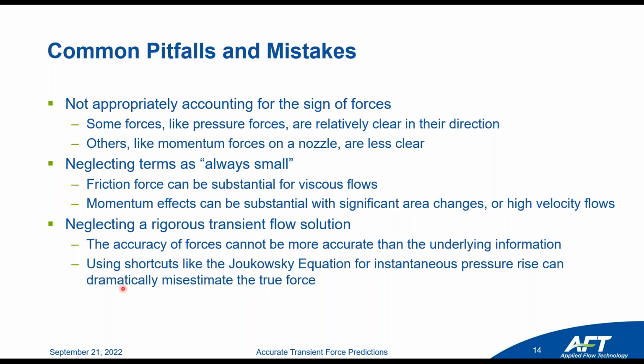That can dramatically misestimate the true force. And I say misestimate here on purpose because you could get a force that is lower than the actual force here. You could also get an estimated force that's much, much higher than what you would really see, causing you to spend way too much money on your support system. So you don't really know, again, until you actually do a true transient solution, what those true forces would be.